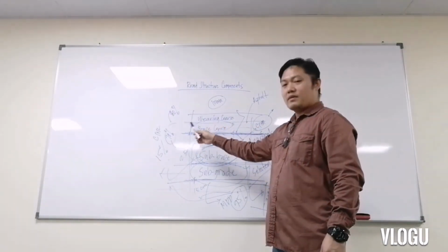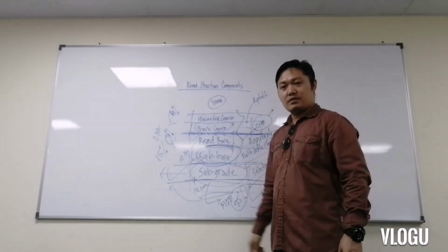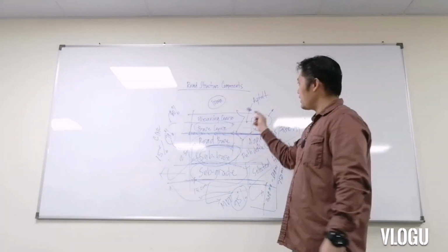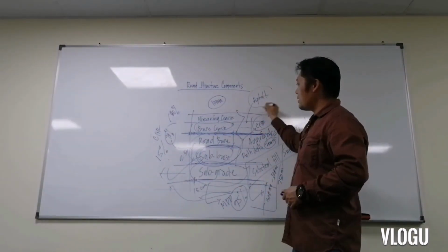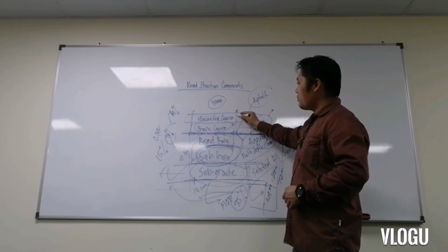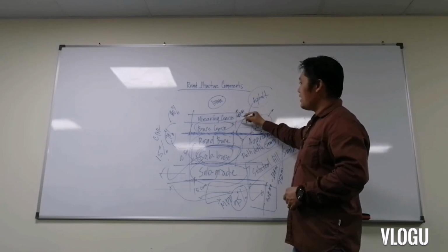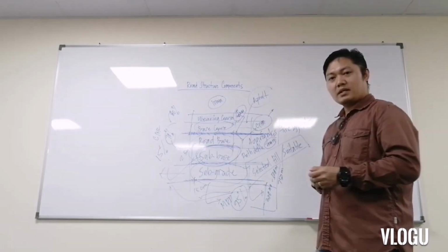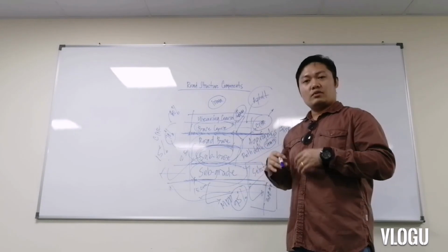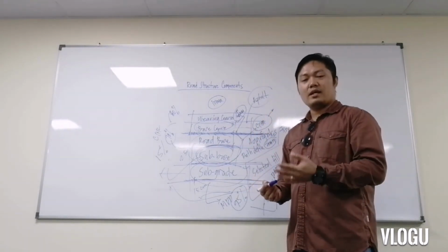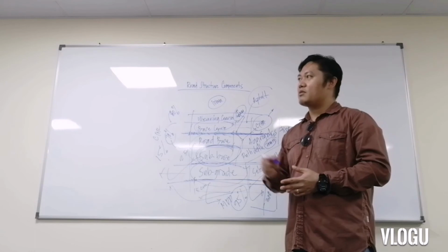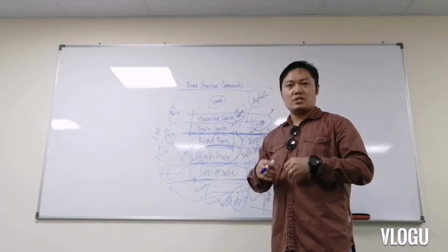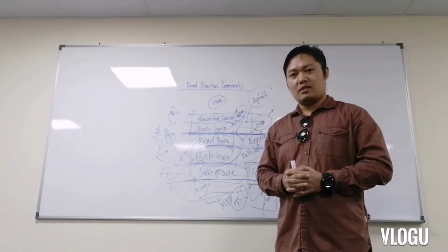After we complete all the parameters and all the testing has been done, we can proceed to the next layer, which is known as the wearing course. The wearing course also depends on the types of material to be used. Normally, in the design, the thickness of the wearing course is a maximum of 50 mm. That is the requirement. All the testing parameters are carried out with respect to the project specification, the job mix formula, and the asphalt conformity certificates issued by the government.